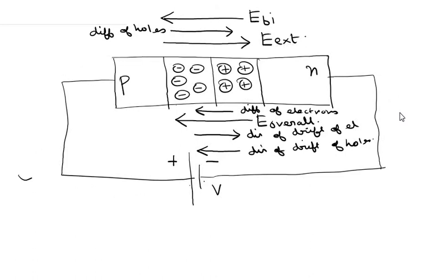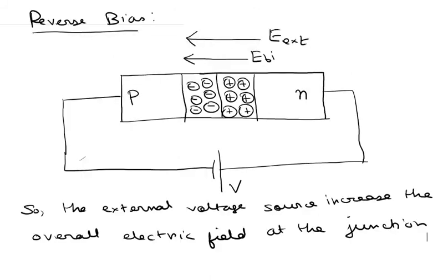On the other hand, if the voltage direction is reversed, as in the reverse bias situation, as we noted, before breakdown no current can flow. So in the reverse bias situation, current cannot flow from the N side to the P side. This flow is prohibited before breakdown. So current cannot flow in the reverse bias situation, and current can flow in the forward bias situation from the P side to the N side.